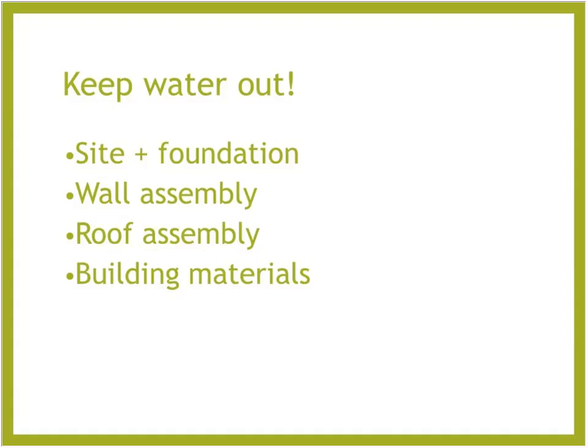If you're finishing an existing basement, you do want to do something like a bulk moisture water test to, number one, determine if there's moisture present in the basement, and then seal it and get it out of there in existing homes. It's very important. Most building scientists recommend just leaving basements alone entirely, not finishing them, because they're usually doomed to fail regardless. There's a lot of technology out there that can be used to avoid that. That's just the first thing.